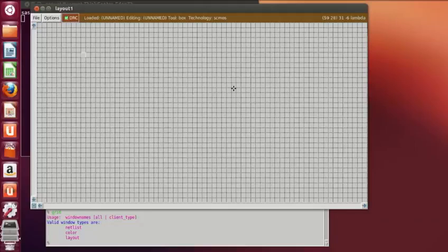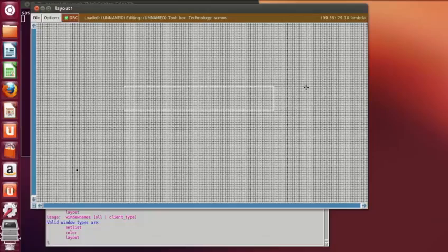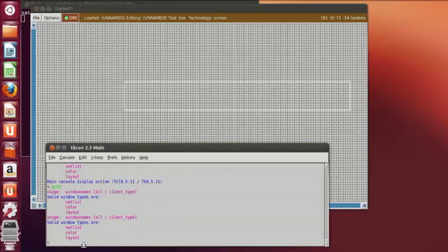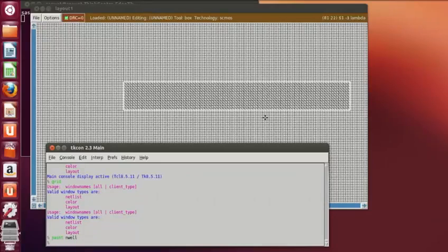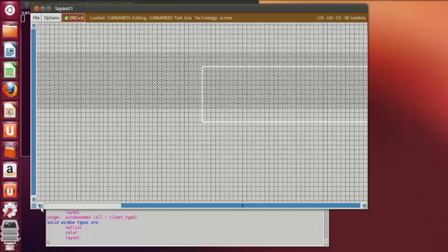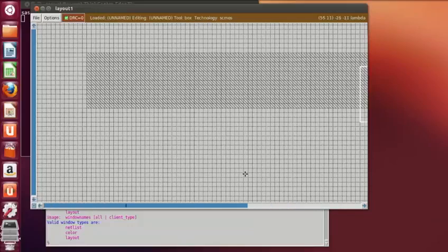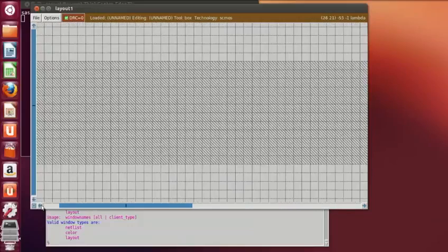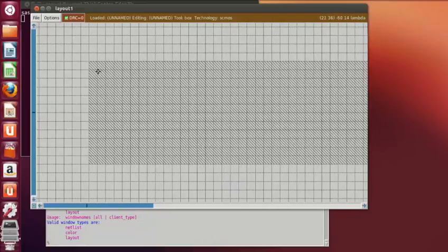In order to draw the PMOS, select the area, zoom out, select the area and type paint nwell. Okay, now there will be 4 P diffusion.